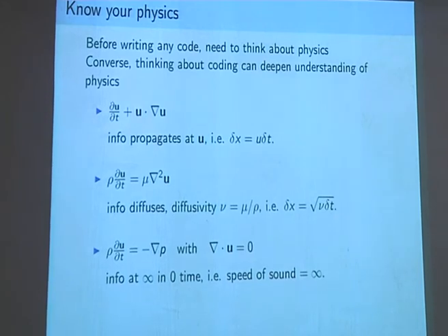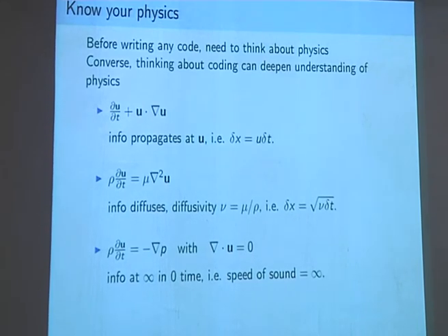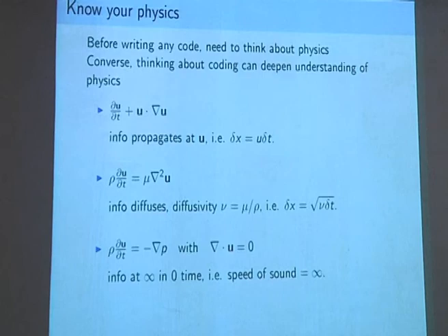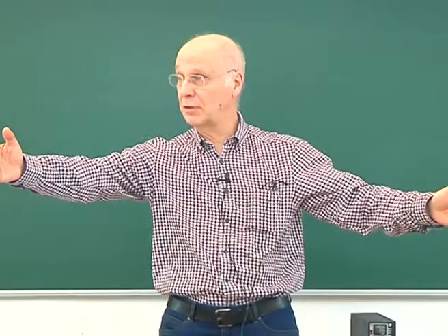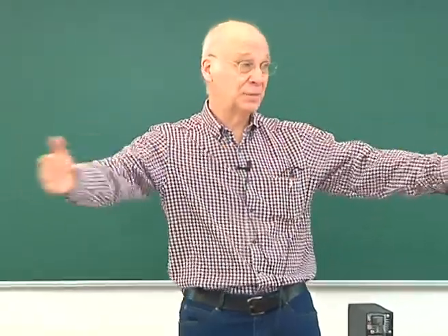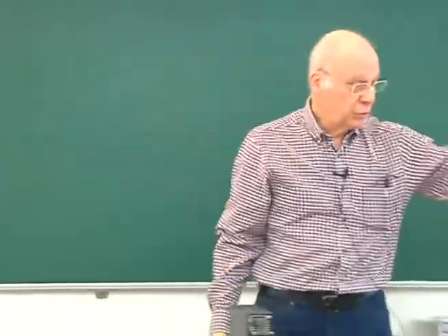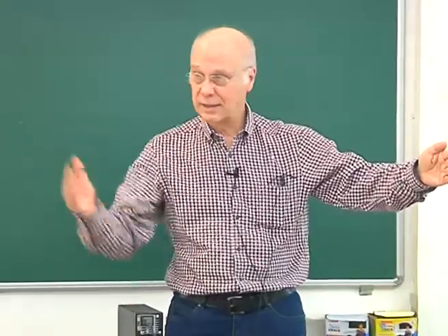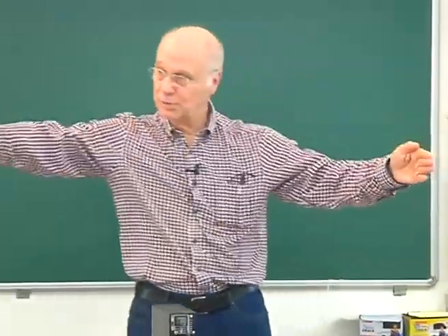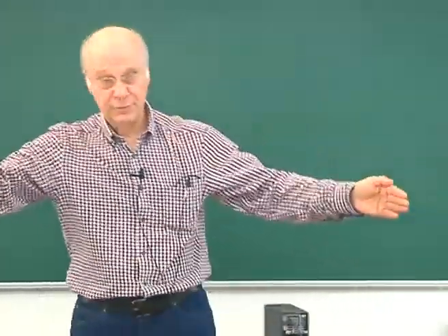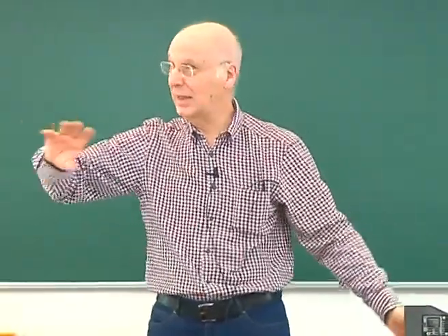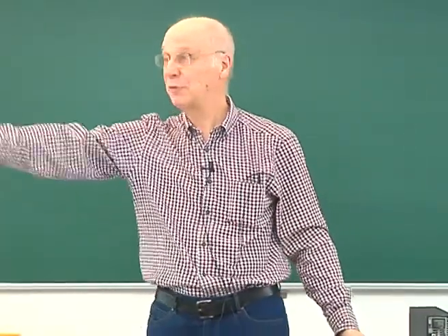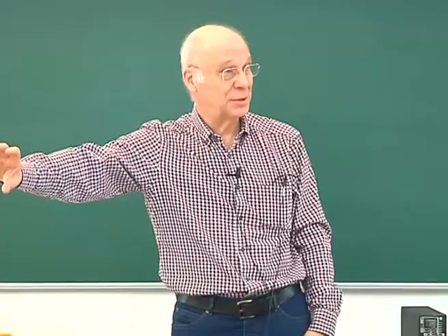And so this part of the equations can send information from one side of your experiment to the other side in zero time. We've put the speed of sound equal to infinity. If you push a wall sideways, or in a tube, if you push the plug, I'm afraid the fluid comes out the other side instantaneously, however long the pipe, if it's incompressible.